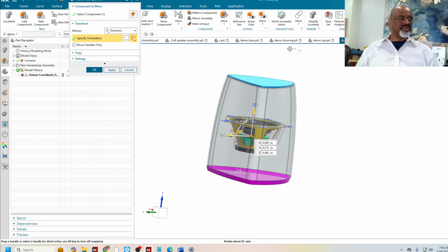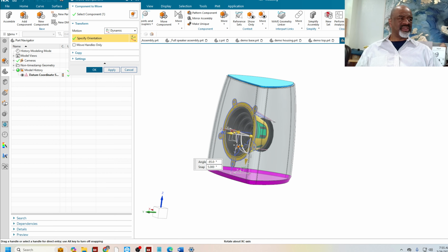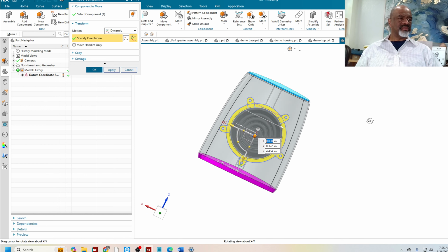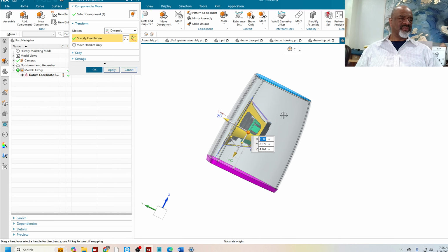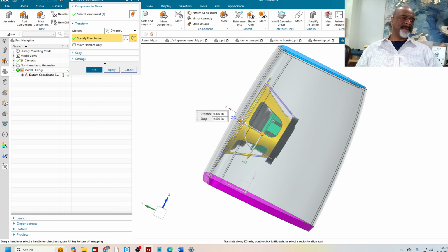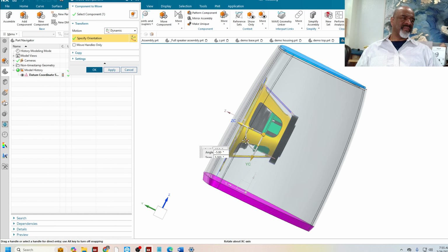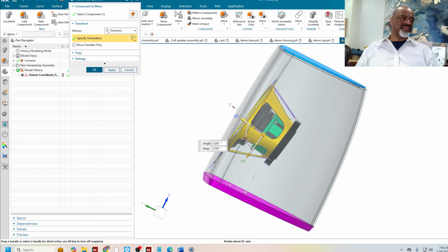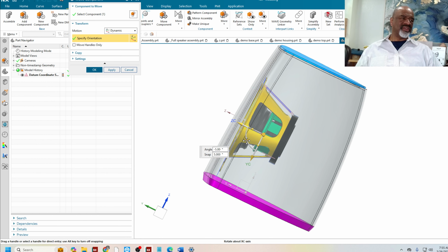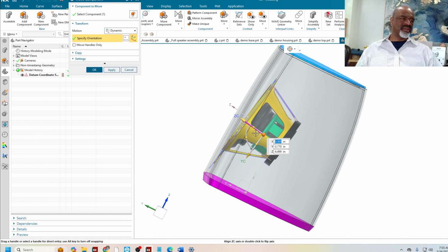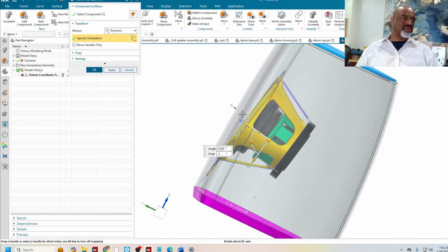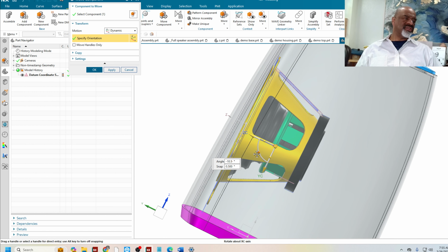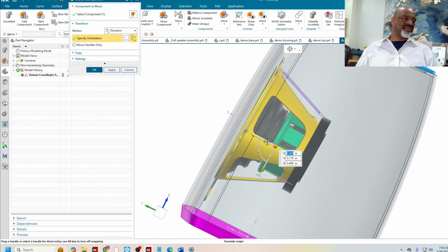Then we can experiment with the orientation of this and we can get it so it's perfect. I like that. I want it to be tilted a little bit with the wall. As you can see, it's snapping in a way that's stopping me from getting it perfect. So I'm going to click on this little BB here and give it a snap angle of 0.5, so there's better resolution. So now I can, that is perfect.